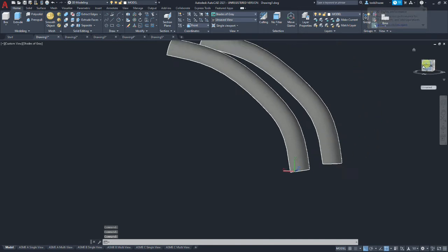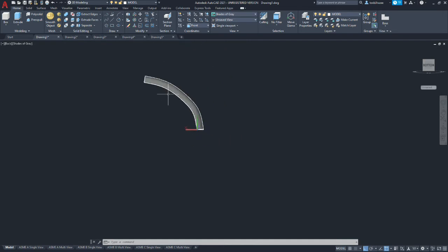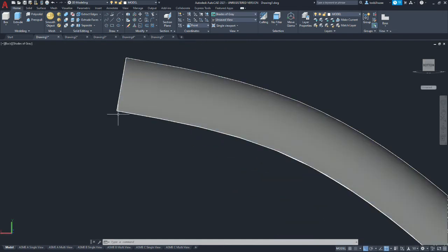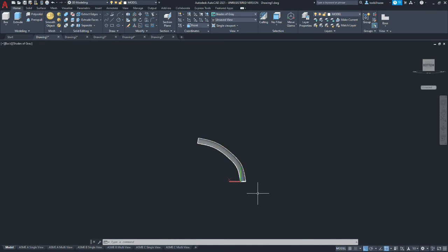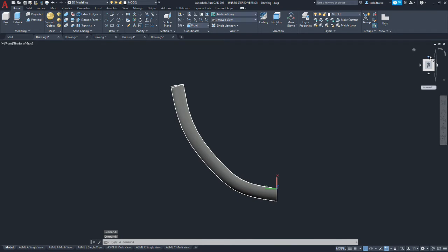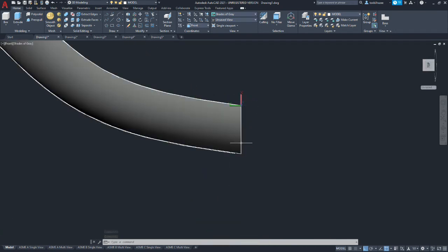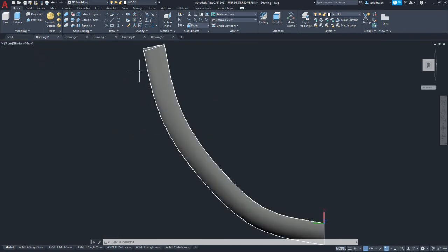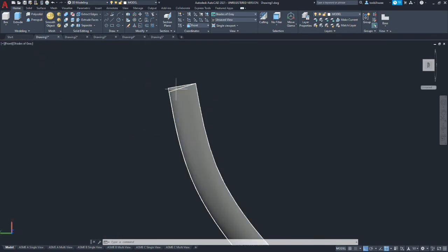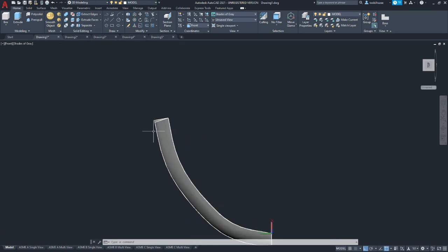I'll look at the bottom view. So the first example, which is default, it takes the curve in whatever plane it was in and tilts it 90 degrees to the path so that it always has a 90-degree termination on either end. If we are to look at the opposite side, the path stays in orientation of what it's drawn the entire shape. So you have a difference in the end termination that's not 90 degrees. It's in relationship to the twist of the path.